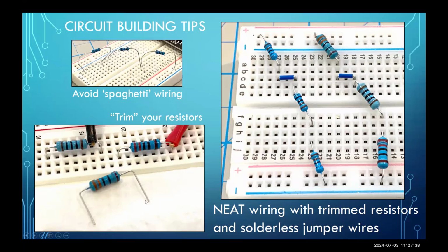By trimming them to half an inch, it will allow the resistors to go fully onto the board, yet stick up just enough so that you could put a little mini hook for a probe onto the side of the lead of the resistor. So here, the bend allows for a connection of the mini hook to the left and right sides of the resistor as they come directly out of the resistor, or you can also connect it on the down post of the resistor. This is easy to do, and you only do a few at a time.